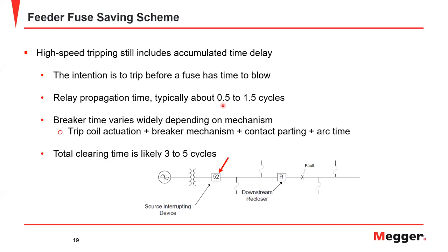It's going to run between 1/2 and 1.5 cycles depending on the relay. The newer relays hitting the market now are getting a little bit faster than this. They use static outputs and they can switch on. I've actually seen one down now to 0.2 cycles.